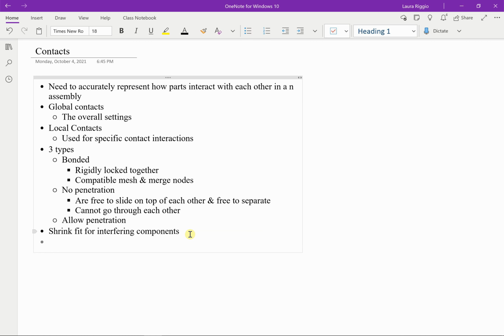And then one last thing to note is SOLIDWORKS sets your contacts based on surfaces that are touching. So small gaps can cause issues. When you're drawing your CAD model to allow for tolerances, if those 2 faces aren't touching, SOLIDWORKS isn't going to automatically find that as a contact, and then if a force is applied to one body, it's not going to transfer to the second body. So you really have to be careful when you model assemblies to make sure all of your contacts are accurately being portrayed.